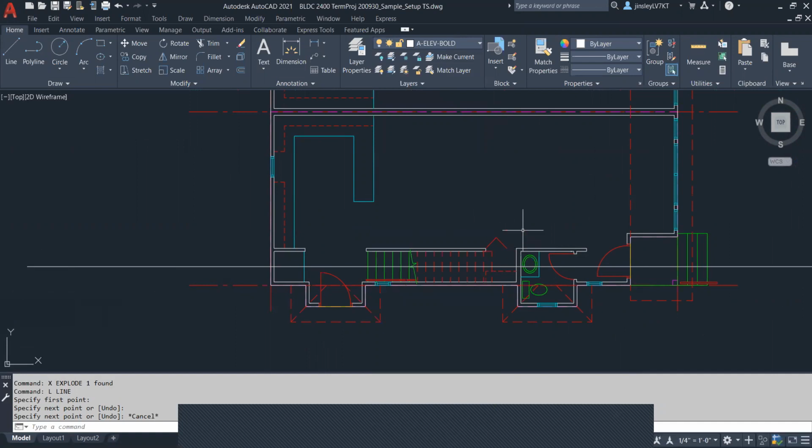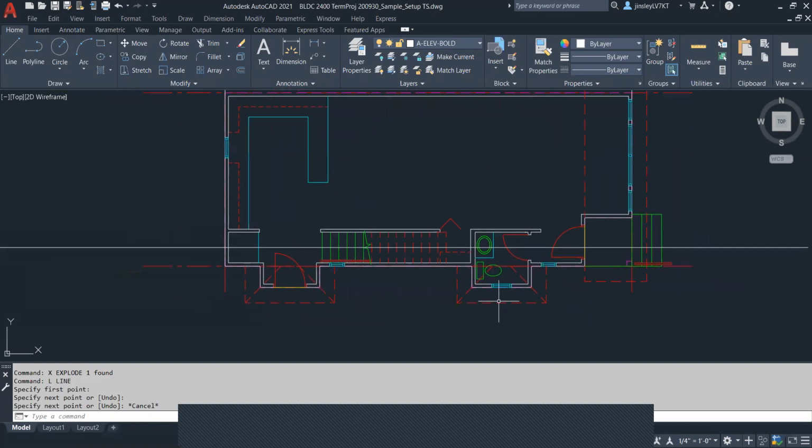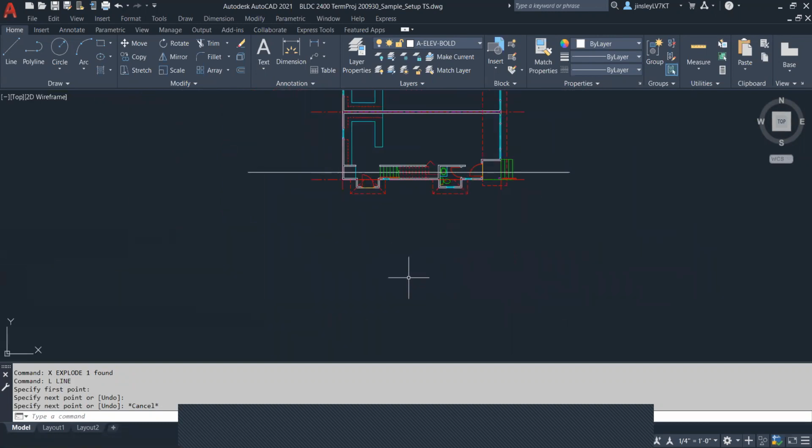Starting with my bold layer, the next thing that I would do is I'm going to mark out the heights of the first floor, second floor, and underside of roof. I can also mark the bottom of the stairs here if I want to as well. So the first floor would be 0. The second floor is 9'11" above.